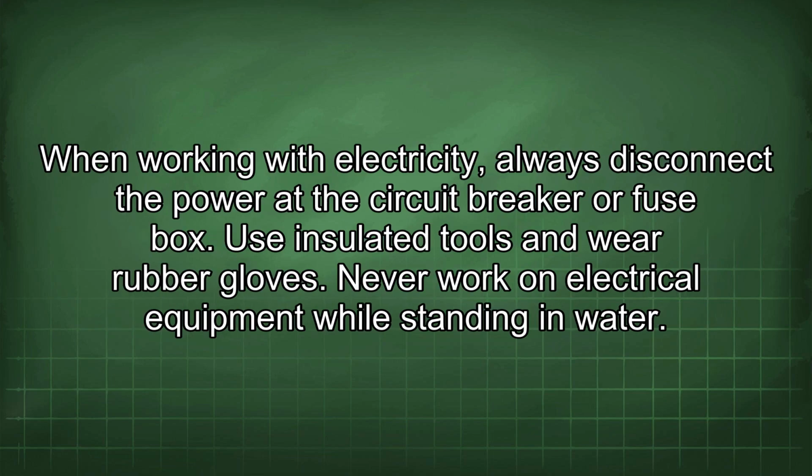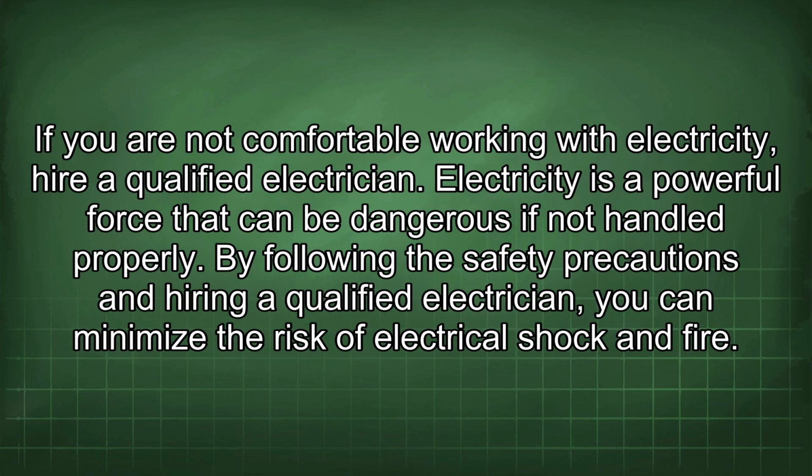When working with electricity, always disconnect the power at the circuit breaker or fuse box. Use insulated tools and wear rubber gloves. Never work on electrical equipment while standing in water. If you are not comfortable working with electricity, hire a qualified electrician. Electricity is a powerful force that can be dangerous if not handled properly. By following the safety precautions and hiring a qualified electrician, you can minimize the risk of electrical shock and fire.